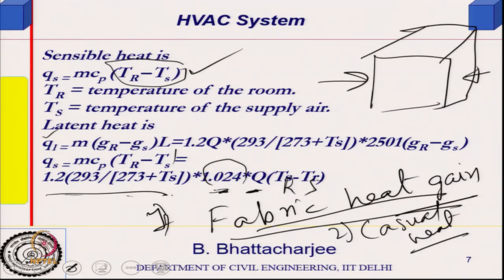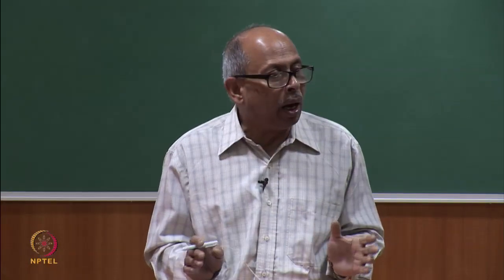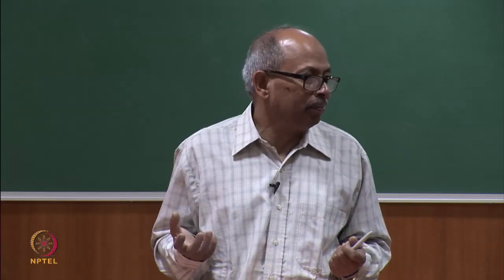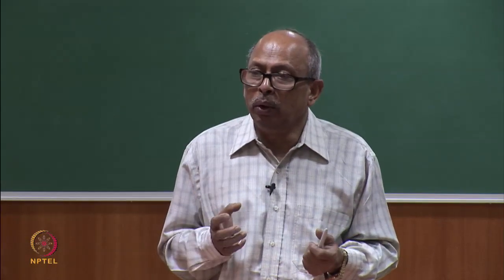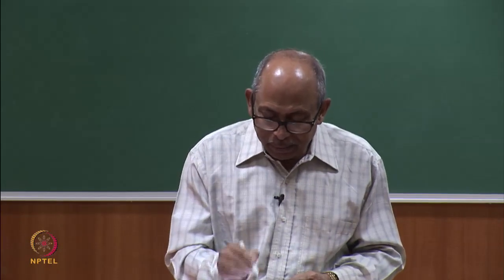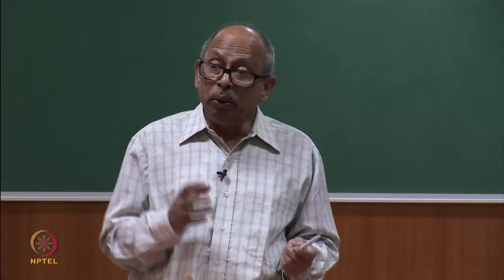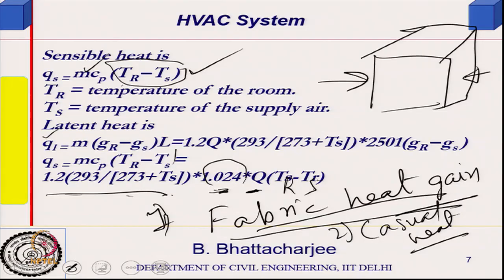What is that principle? Because if you make this differential too large, then the insulation required will be more. So, the cost of insulation will increase, and if you keep it too low, then the flow has to be higher. So, duct sizes will increase, and if you want to keep the duct size lower, the velocity will then increase, the noise could be there. So, based on this it is by and large fixed. We first decide that okay, we will keep a 10-degree differential or 8-degree differential, some differential we fix it up.